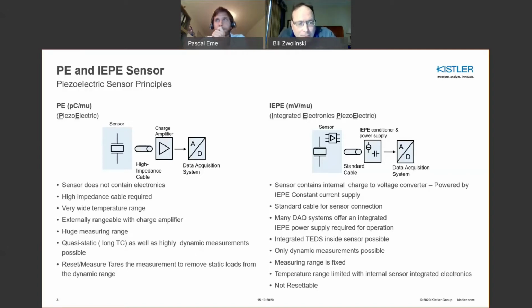You also get the ability to vary the low frequency and high frequency, because there are usually filtering options, and also to do quasi-static measurement. For example, preloading force sensors or very low frequency measurement could very well be done with piezoelectric. So we're going to focus on that technology for this session with the space applications.